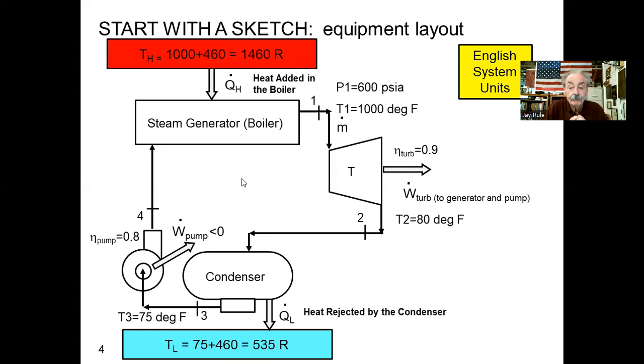We've just spent 4 minutes talking about the sketch, but do you see that if we didn't draw a sketch and didn't label our states, an engineering solution really would be useless to anybody other than the author? And in fact, if you were the author and you went back 3 weeks later to look at your work without a sketch, you wouldn't remember what H1 was or H2 was. Got to have the sketch.